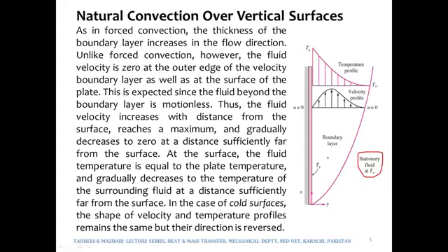Slowly and gradually the fluid will start getting heated up due to the existence of the plate, or cool down, whatever the case is, and due to that temperature difference there would be density differences within the patch which is near to the plate, near to the surface, due to which the fluid will start moving upwards if it is getting heated up.